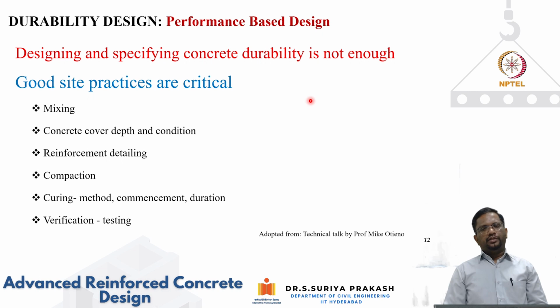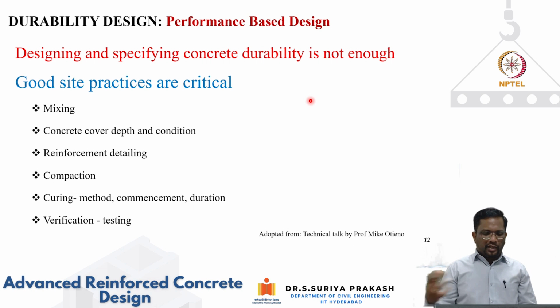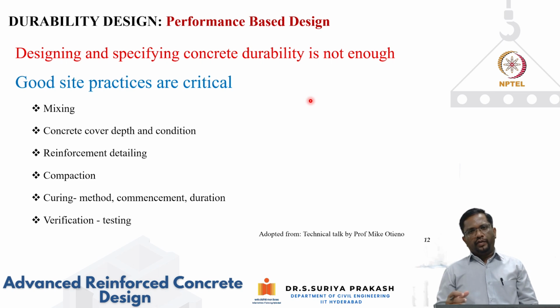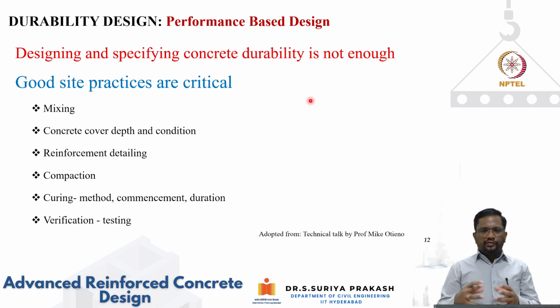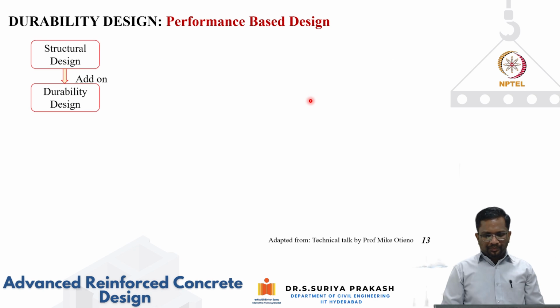And verification, this is the most important thing. Most of the time, at least in India, I think a lot of testing is done before construction, but we don't really do testing from the as-built structure. So we should verify by having a mock-up structure or taking samples from the as-built structure to verify this durability property. So this is also important.